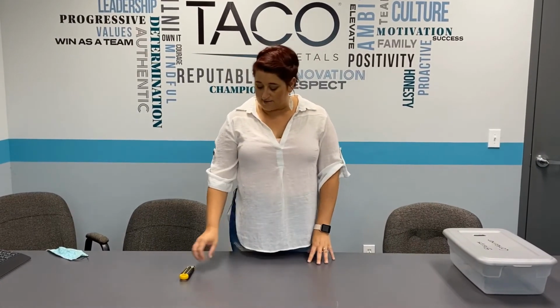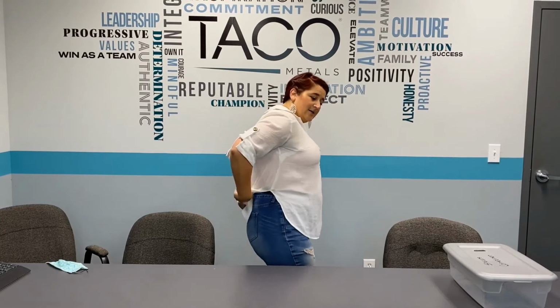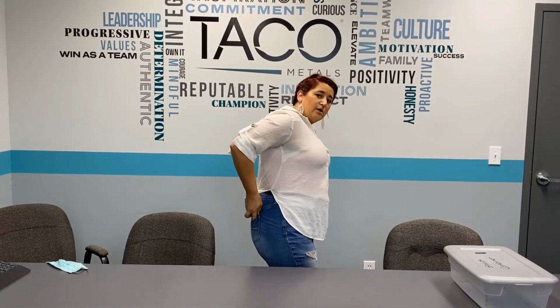One of the other issues that we face with box cutters is the storage and the carrying of these. So one of the things that we want to make sure of is A, it's always closed. B, you never put it in your pocket. You do not put box cutters in your pocket, because there could be a time when you forget about that.